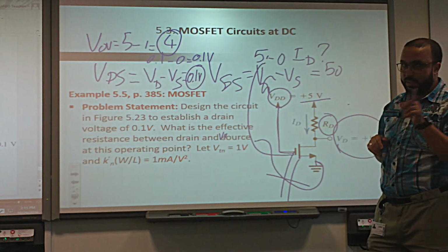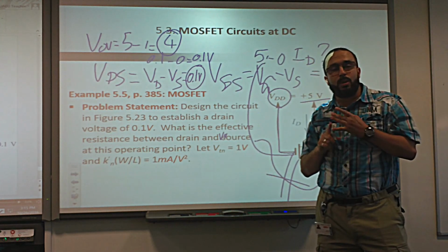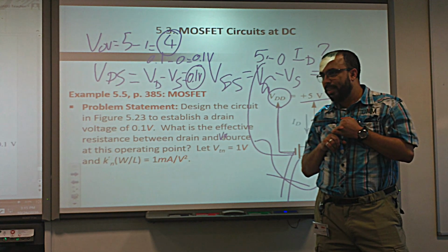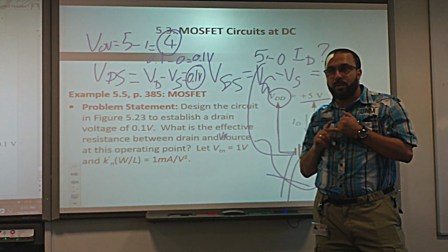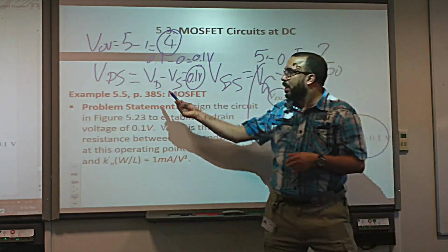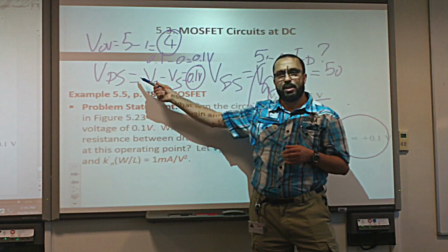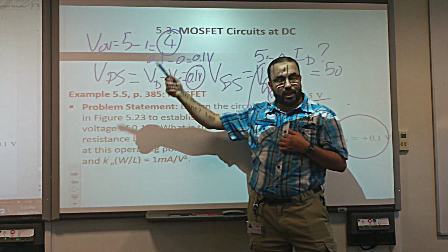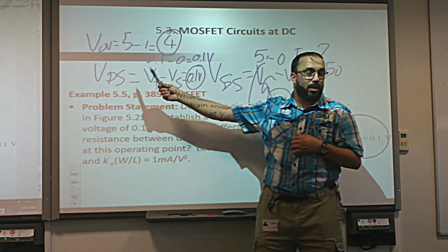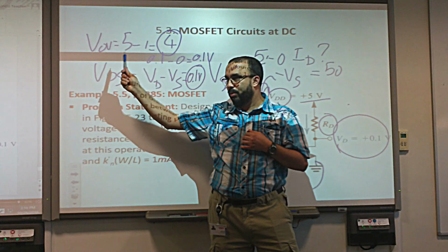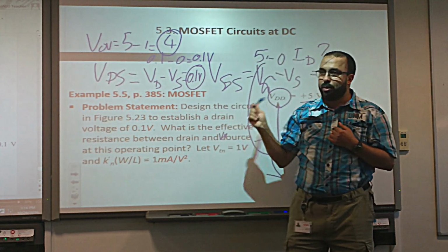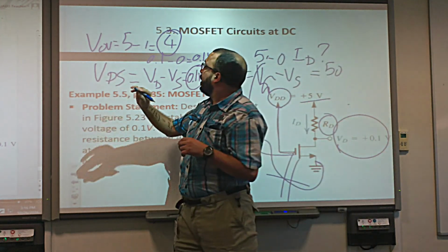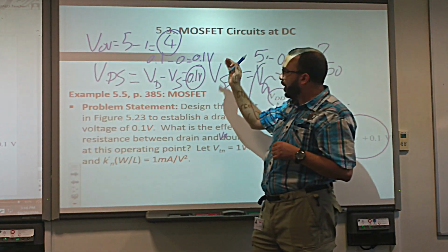You understand? See how we do it? So we need to know where the MOSFET is working. This is number 1. We have to know how to calculate these voltages. This is not a joke. This is serious. These are the basics of electrical engineering. VDS, VGS. Please do not ask me how to find VDS and VGS. You look at the circuit, you know what VDS and VGS mean. Then officially we are in triode.